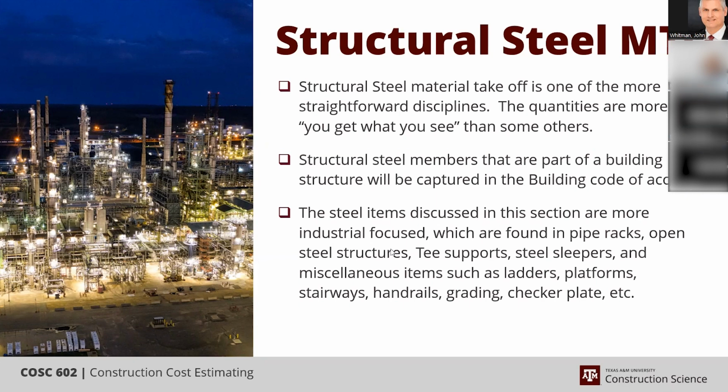Yeah, I just had one question about the project we just did. Were we supposed to account for forms in that NTO that we did, or were we just doing the NTO for the actual assemblies that we saw? Yes, forms would have been part of it, because you have to quantify the forms you need to rent that become part of the cost of installing the foundation. Okay, thank you. You're welcome.